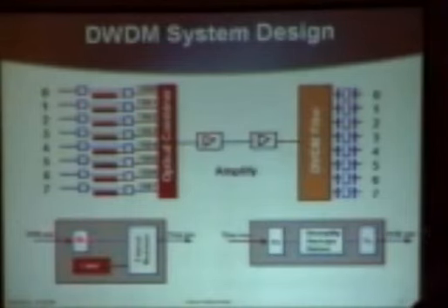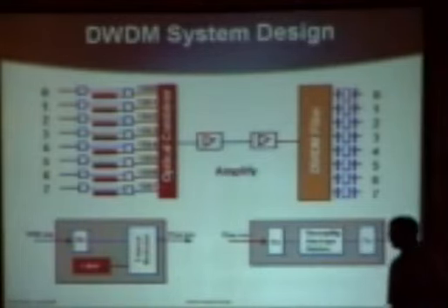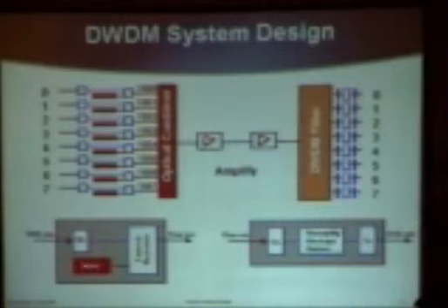That signal is terminated, and it electrically drives generally an external modulator, which means that there is a precise wavelength laser, say 1550 or 1551, that is being driven through the modulator, and the modulation is being applied electrically to that new carrier. So coming out here is exactly the same electrical signal that went in over here, but it's then converted onto a specific wavelength for multiplexing into the long-haul network.